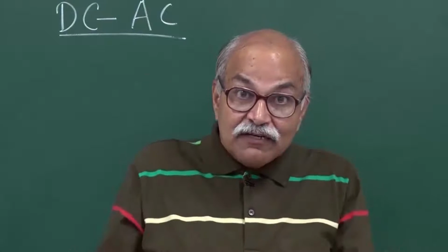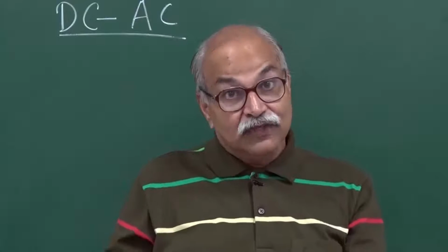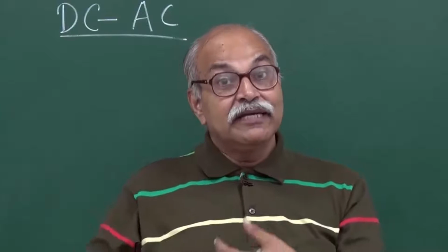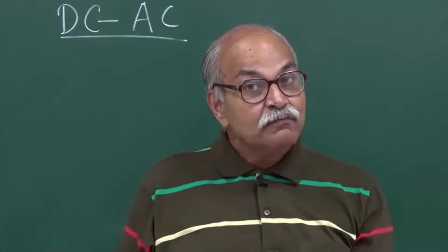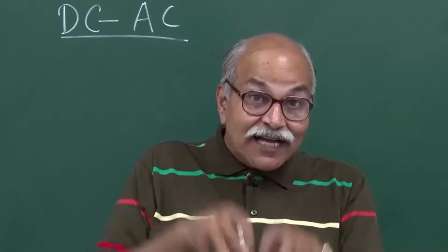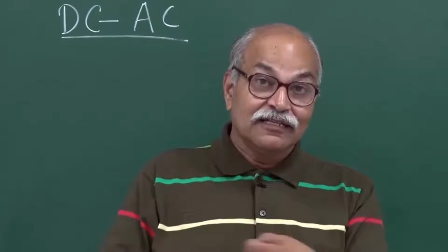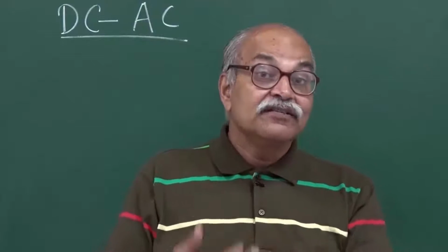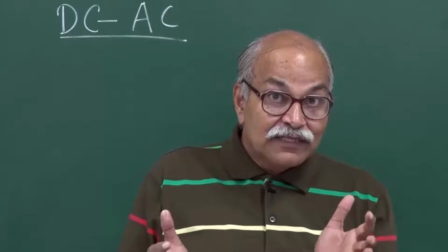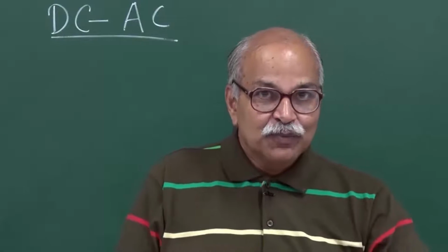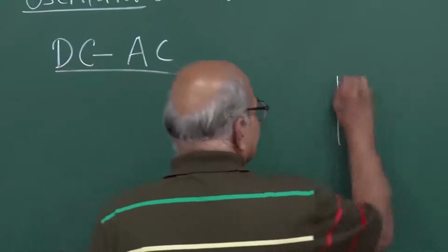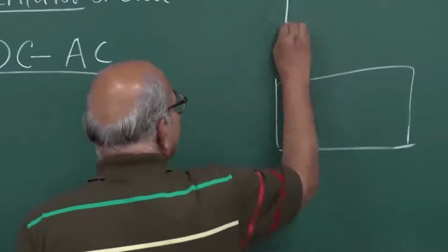So, I need some kind of a circuit which, once started, we do not give any external AC of that frequency, but by itself it can pick up a frequency, and at that frequency voltage or current in that unit should oscillate. That kind of circuit, a frequency selective circuit, should be one essential part.